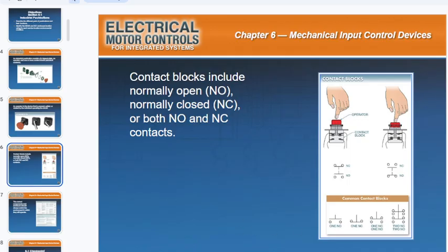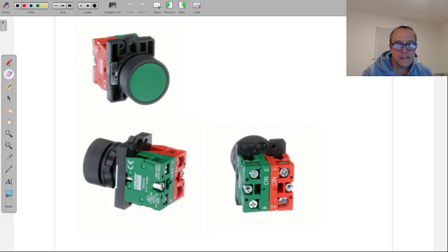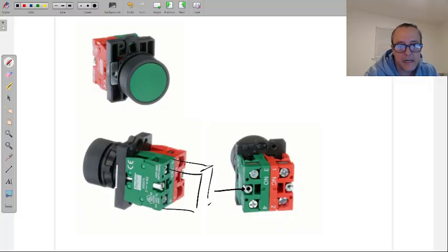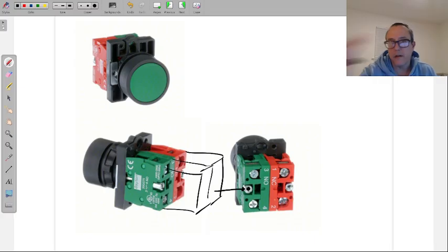That's the other thing, by the way, just to show you these a little bit more close up. These contactors, all of them have, I'm not sure if you can see it that well from the image there, a little hole inside the screw behind it, and that is threaded. What that's for is so that you can take this screw that's holding that contact and screw it into the back of this as well, and you can build an extended contact block. So you can put another contact on top of a contact. Essentially I can have 4 back here if I wanted: 2 normally open, 2 normally closed.